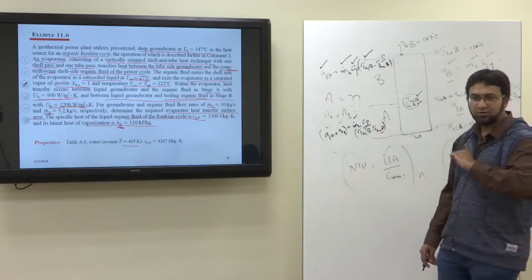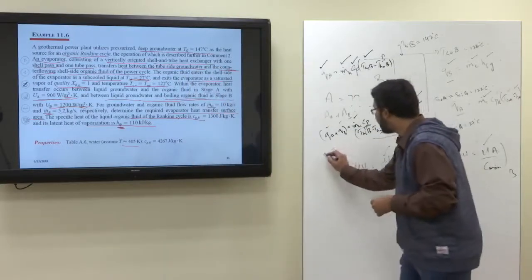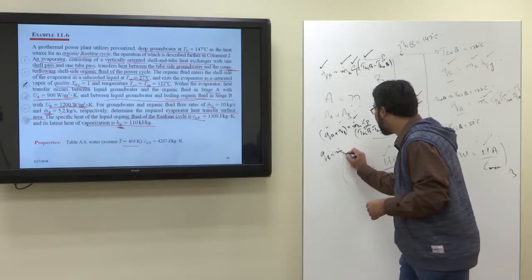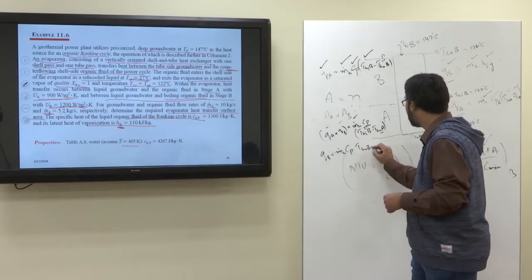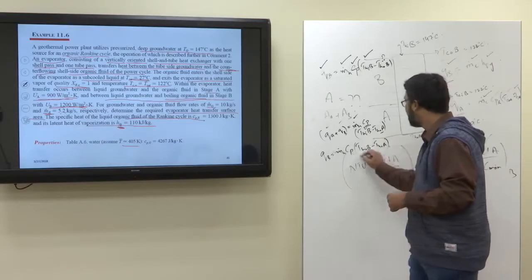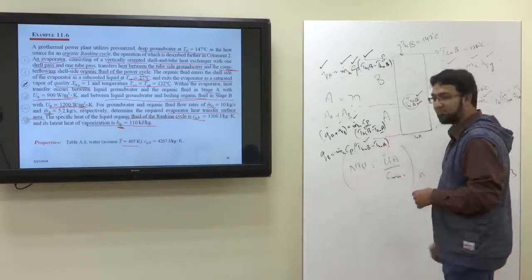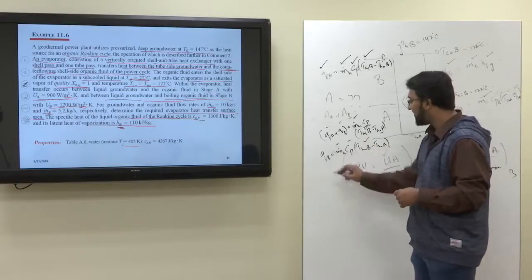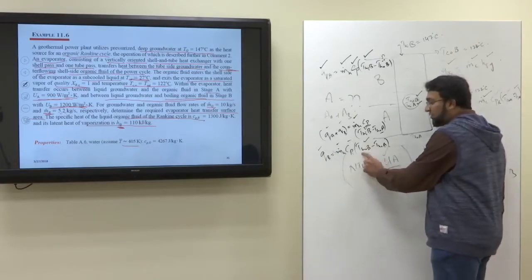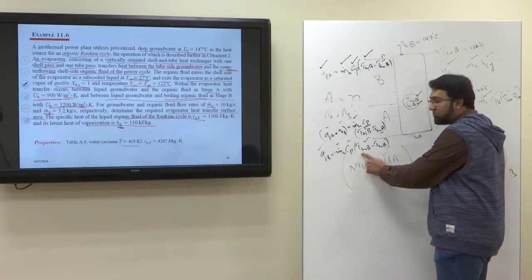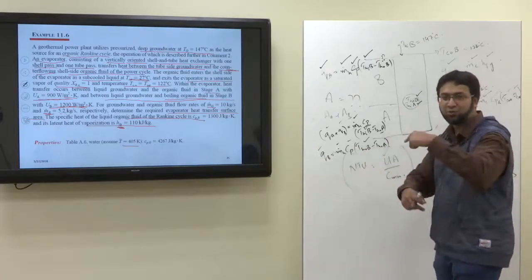If you just use QB, I cannot do it wrong in the exam. Let's say you just use QB. So what will be the formula? QB will be m dot h Cp, T hot outlet B minus T hot outlet A. Right? T hot outlet B equals T hot inlet A. So we know this thing, and we know Cp, we know m dot h, we know QB. You can find T hot inlet A. But in this case, there is a chance of error in THOB. So there will be chances of more error in THOA. Error will be accumulated if you are already using an error value.